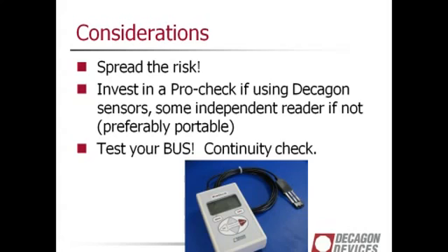Try to find some way of independently reading sensors if you're not using Decagon sensors, preferably portable. It's nice to just be able to go out, unplug one sensor, and test it and make sure it's doing what it is supposed to be doing.